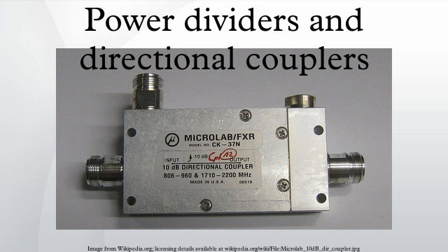A portion of the power applied to port 2 will be coupled to port 4. However, the device is not normally used in this mode and port 4 is usually terminated with a matched load. This termination can be internal to the device and port 4 is not accessible to the user. Effectively, this results in a 3-port device, hence the utility of the second symbol for directional couplers in Figure 1. Symbols of the form in this article have the meaning parameter P at port A due to an input at port B. A symbol for power dividers is shown in Figure 2.